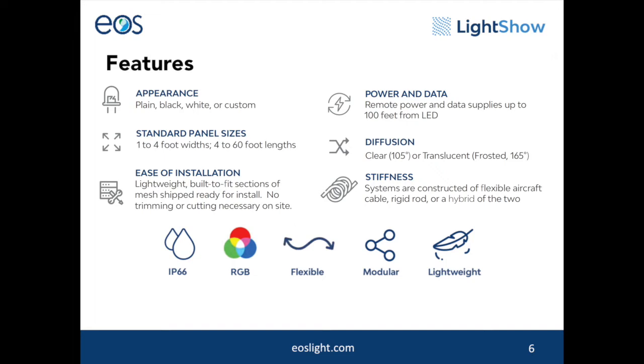Panels, which refer to the individual sections of LightShow and LightShow Max, are built to size prior to shipping, so there is no need for trimming or cutting upon receipt. The use of remote power and data supplies makes for lighter, easier to handle panels, which can simplify the installation process. Remote power supplies may also be easier to troubleshoot post-installation.